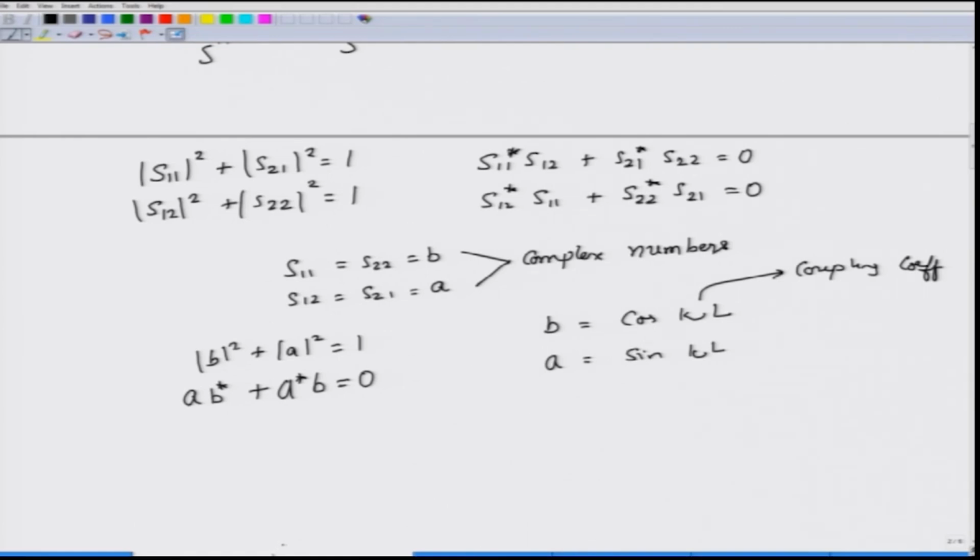Okay. Now, if you substitute B and A into this second equation, it will give you a relationship. Actually, we have to also consider them to be complex numbers, right. So, we will multiply B and A by certain phase angles, e to the power j phi b and e to the power j phi a. My magnitude square will remove the e power j phi b term and e power j phi a term, and therefore they do not really change anything in the first equation, but for the second equation they will actually determine what the relationship between phi b and phi a should be.